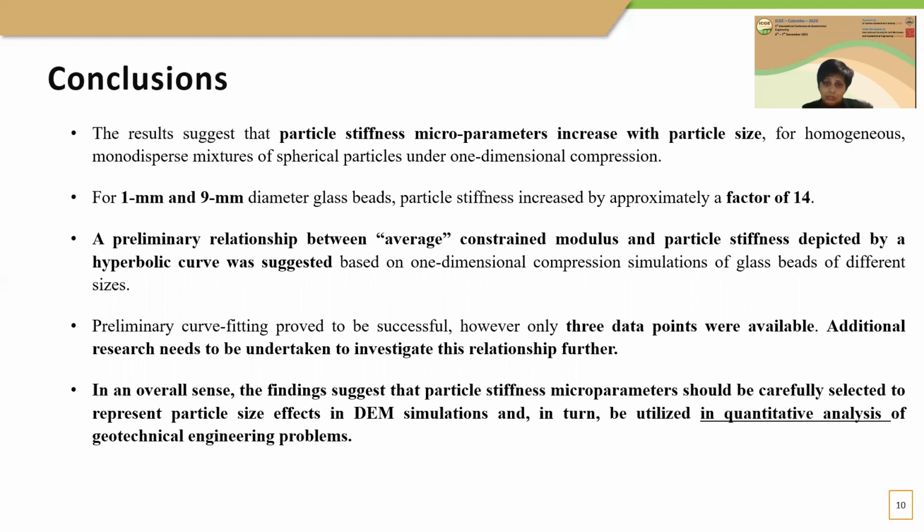However, it's necessary to conduct further studies to confirm this relationship before using that equation. But in an overall sense, the findings suggested that particle stiffness microparameters should be carefully selected to represent the particle size effect in DEM simulations, in turn being useful for quantitative analysis of geotechnical engineering problems.